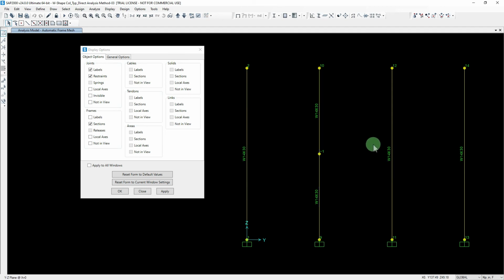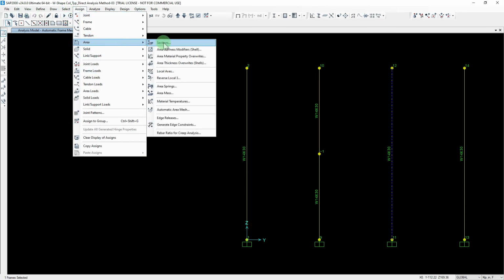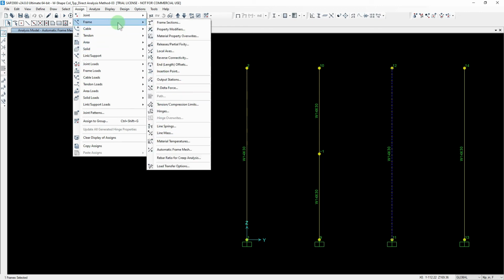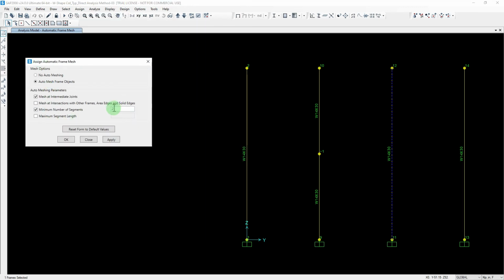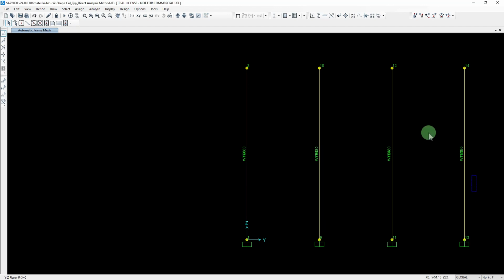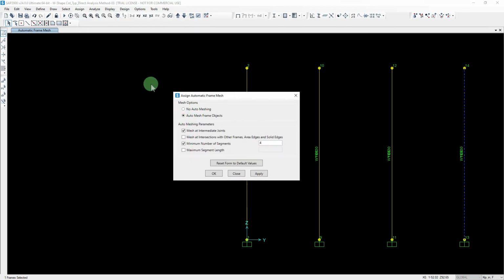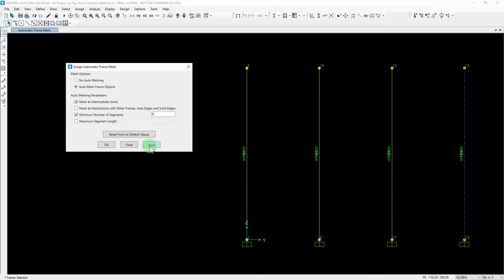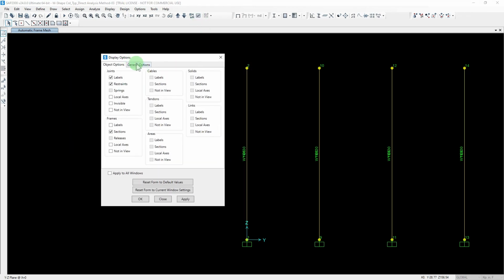Right. I'm going to do this right here, and I will add 4 to this. So we'll just keep multiplying it by 2, keep doubling up on it, and see the effects of that on the design results. So 4. Come over here, we'll make this one 8. Hit apply. Alright, we're almost to the finish line. I'm going to say OK. Again, I'll show you what it looks like as far as an analysis model is concerned.